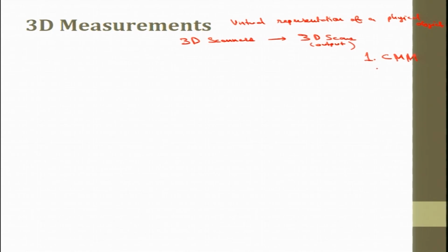The second type of 3D scanner is the tracked 3D scanner. In a tracked 3D scanner, optical tracking devices can track various types of measurement tools, including positioning of a 3D scanner. So the positioning method can be an external optical tracking device. These scanners use an external optical tracking device to establish positioning. They usually use markers such as passive or active targets that optically bind the tracking device to the scanner. Another kind of scanner is the structured light scanner.